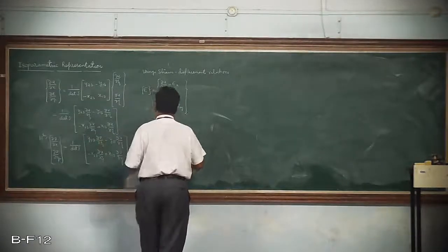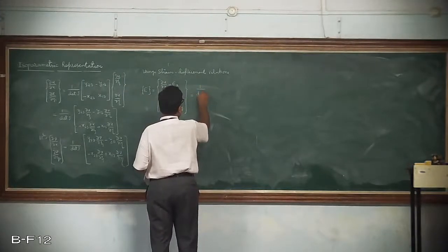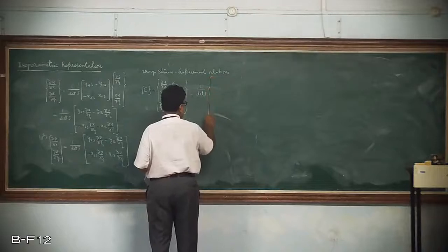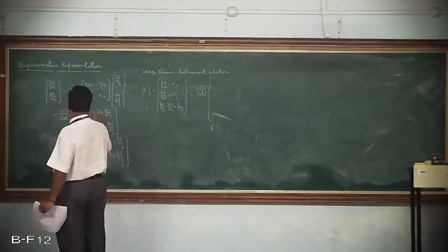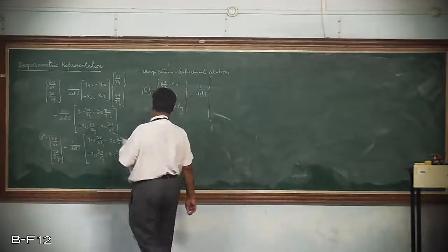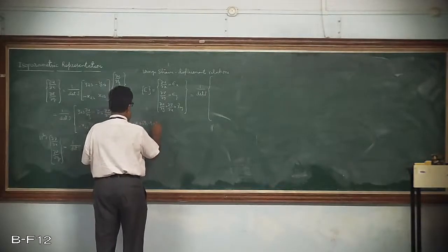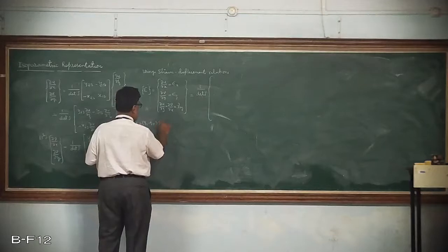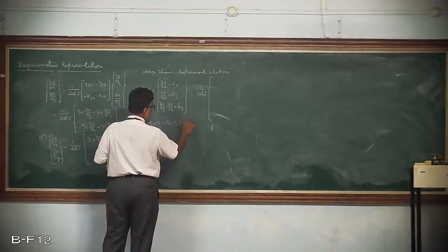So if I open this, what will happen? This will be 1 upon determinant of J, always there. Where is dou u by dou x? Yes, this is our dou u by dou x. So I will write y23. But interestingly, you already know what u is. We have seen in the earlier class, u is q1 minus q5 zeta plus q3 minus q5 eta plus q5.